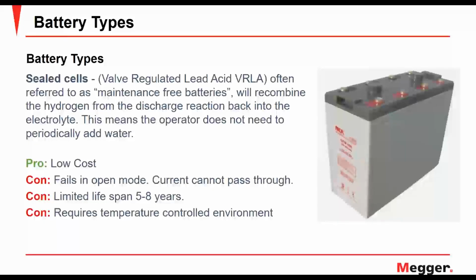They have a relatively shorter lifespan compared to the VLA batteries, and they require a temperature controlled environment, since this process of failure can be accelerated quickly in a high temperature environment, and we will talk about this type of failure in the failure mode sections.